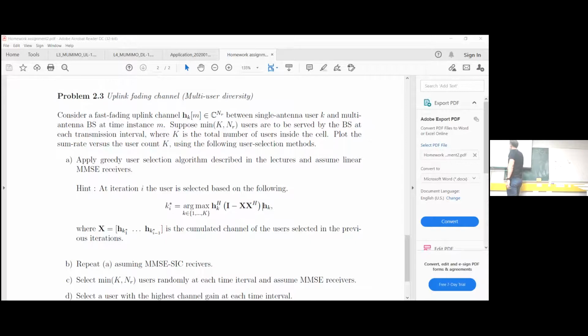Assuming dirty paper coding strategy, for user 2, we can treat the signal vector, which is now in vector domain because it also contains the beamformer U, that was designed for user 3 as something that we can take as side information, right?